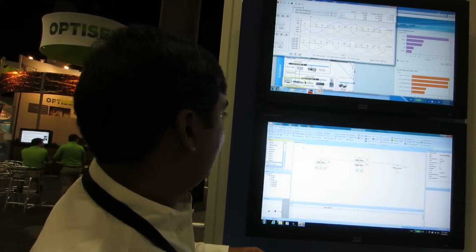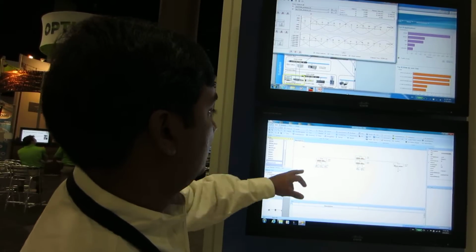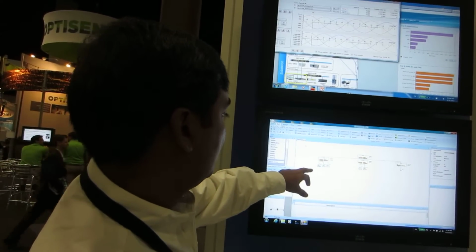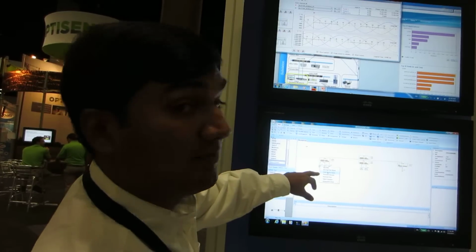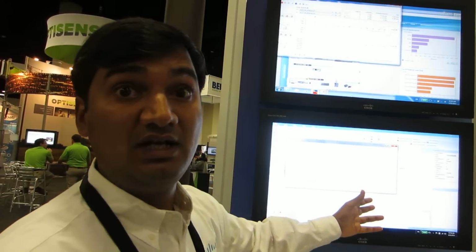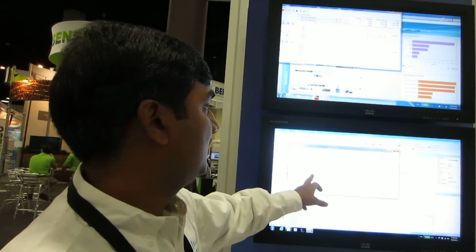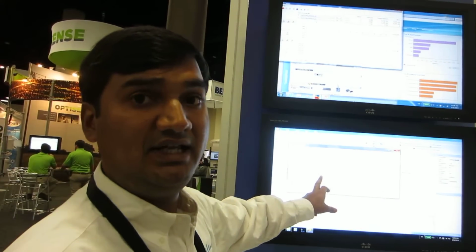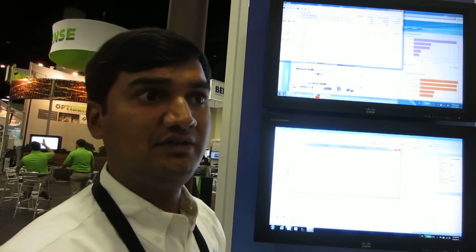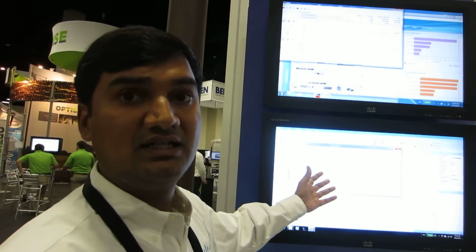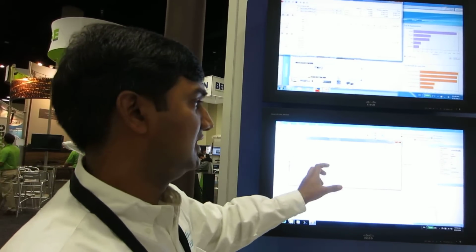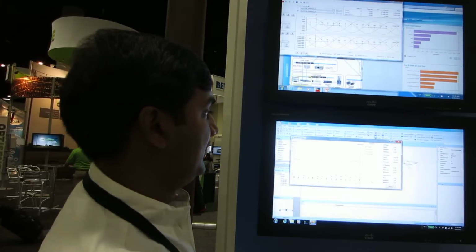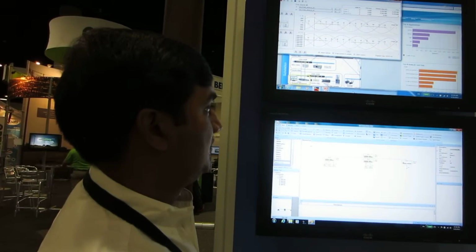I will quickly take you to another view, where you can see the total information coming in and the performance of these IEDs, which you never had before. Like I said earlier, the switch captures all the information. Now you can see the total bandwidth and the packets going in and out of this IED. So if there's an issue, you get to know beforehand that something is happening with this particular IED, and you can take corrective action. Quickly, I will switch to another view.